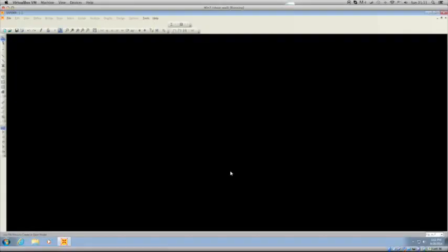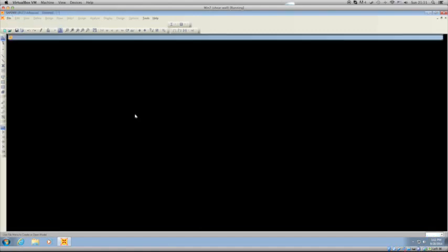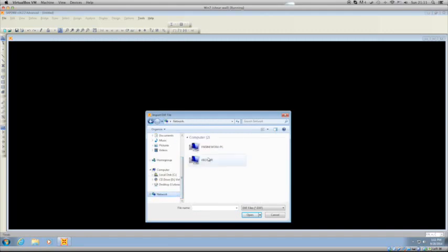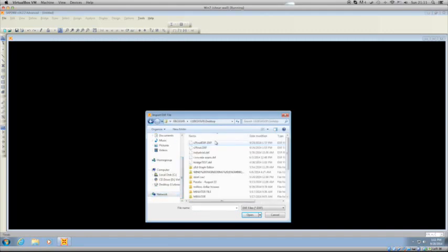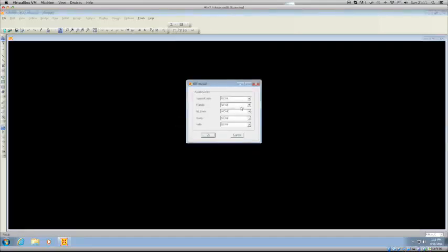Okay, so here we are in the amazing SAP2000. Now, the first thing I'm going to do before I import my DXF is change my units from here to kilonewton meters. Now, let's import DXF of our bridge, and for that I've got that on the VBox server. Bridge test. Okay, so Z is up and we're working in kilonewton meters.